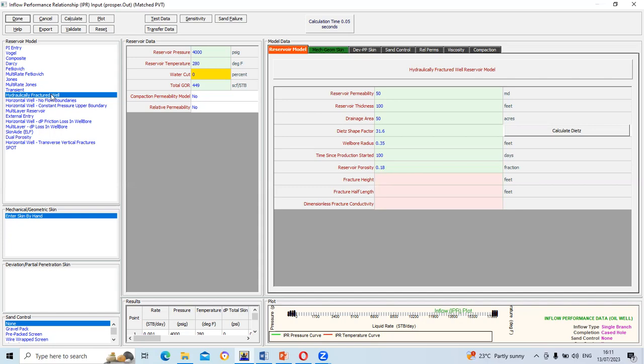That's due mostly to the interaction between hydrocarbon and some other types of fluids within the reservoir that are not compatible. You could have something like fines migration, where finer grains of sand deep within the reservoir are carried by high flow hydrocarbon. But once they get closer to the borehole, the flow rate may drop and they now deposit the fine grains around that area, thereby blocking the pore spaces and damaging the zone closer to the wellbore.